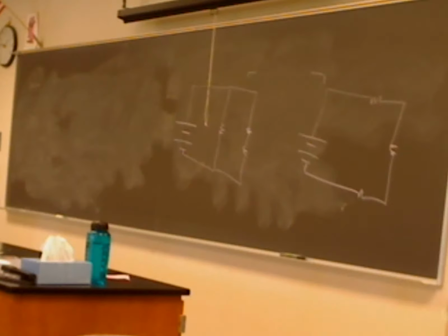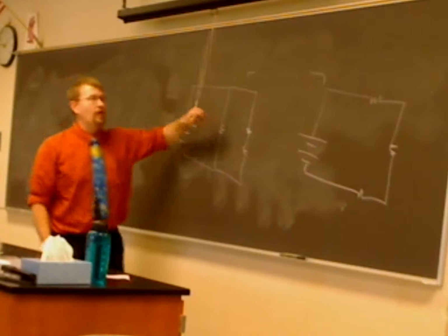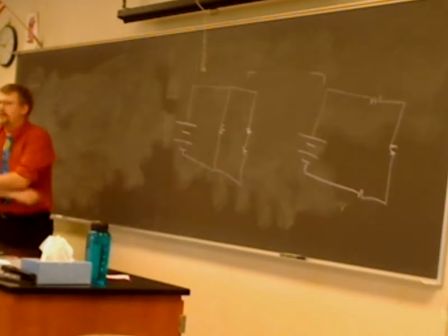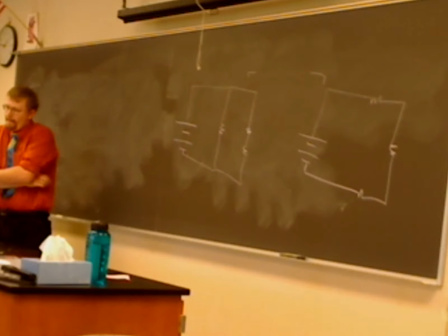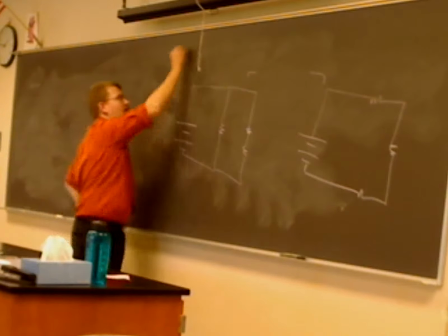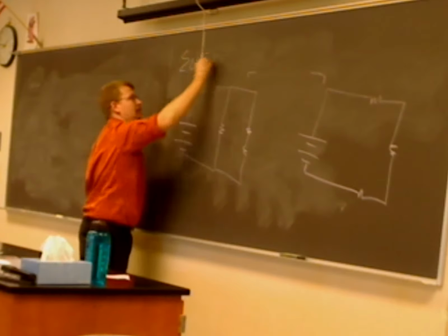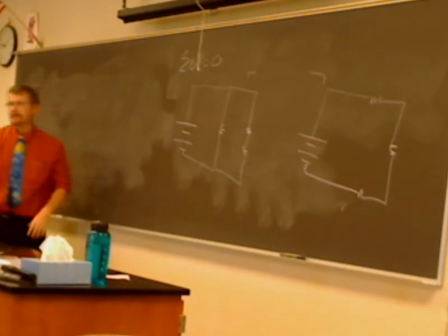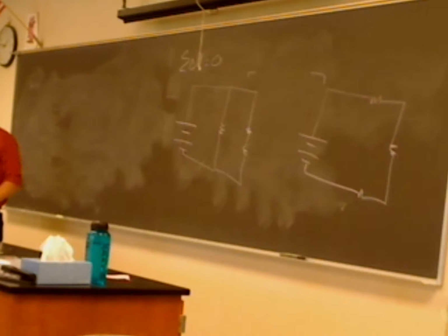So, Kirchhoff gave us two rules. What were those two rules and what were they related to? Anyone remember Kirchhoff? Good, so if we add up all the changes in V around the loop, that should equal 0. Can someone put that into layman's terms for us? Besides saying the sum of the voltage drops equals 0, what does that mean? What does a proton have to do as it goes around the circuit? Lose all potential energy. Good, so it's going to lose all of the energy it got from the battery. Whatever loop, whatever path it takes, it's going to lose all the energy.